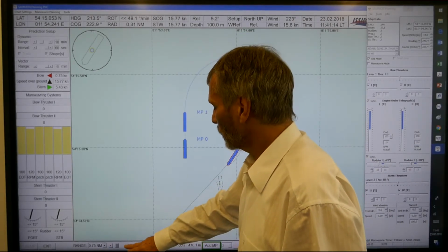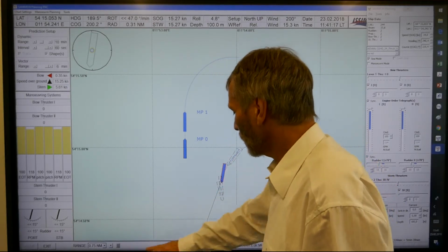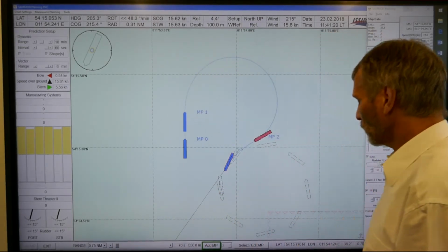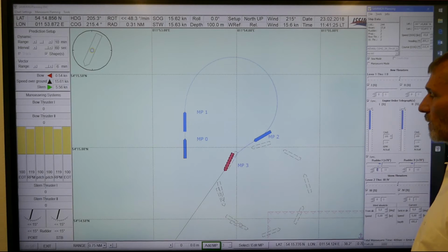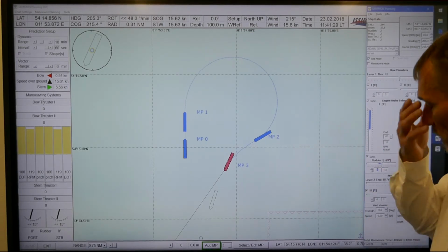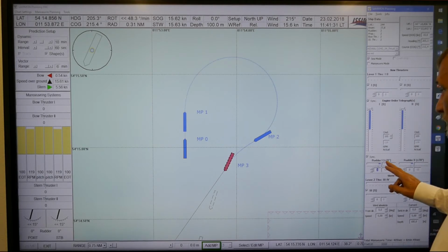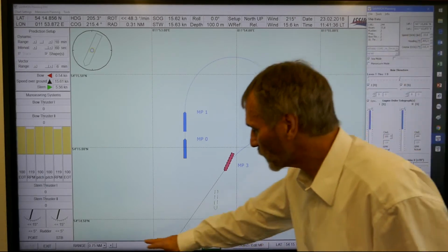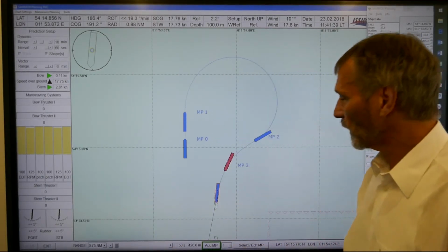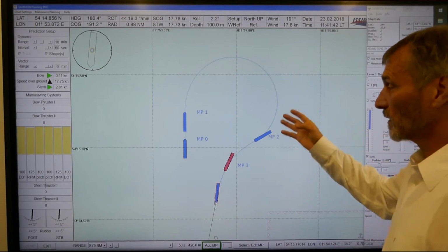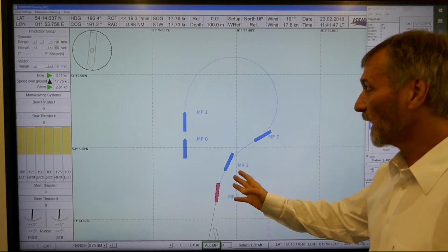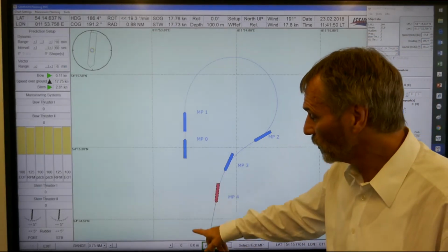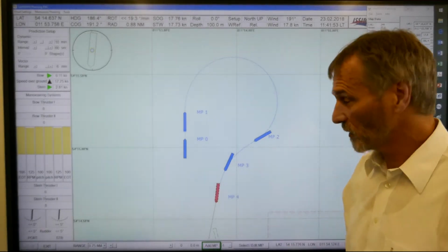We move the ship a little bit to stop it up to here. So maybe we switch it here to rudder midships, maybe a little bit further up. Like this one, so we have to line up the ship here, and then you see, okay, this would be sort of a return maneuver in case of man overboard, but normally we would like to have the ship a little bit more to the initial track to see the person in the water.